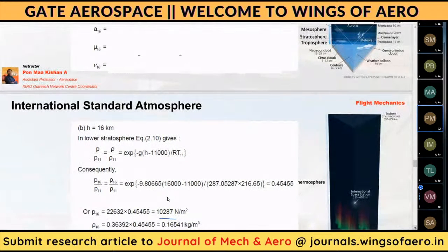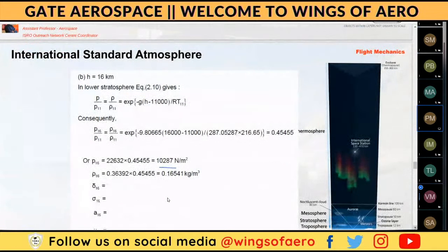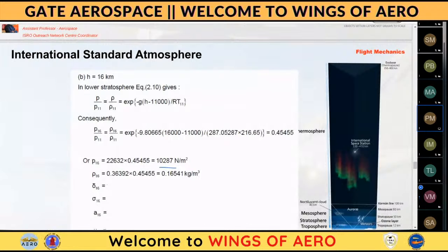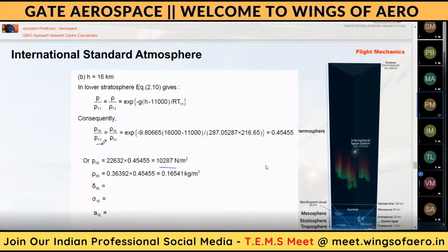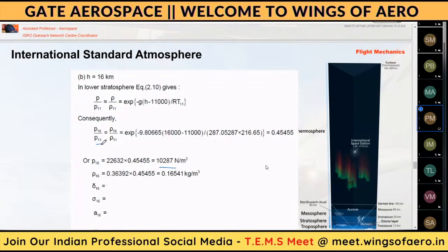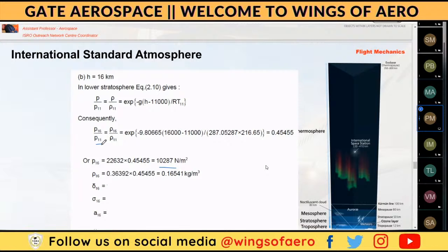So one small doubt, sir. Yes, dear. Like P16 by P11 is equal to T16 by T11, the whole power 5.25588. Can I use that, sir? For what? I'm getting confused. For calculating the pressure at 11, right? Yes, sir. Pressure at 11, you have to use that because that is the troposphere. At that altitude only the tropopause is ending. So you can use that. Okay.